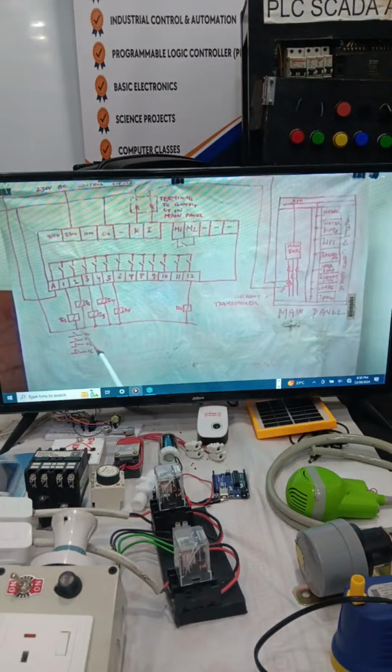To avoid this, we are using one small relay. It will have only small auxiliary contacts, and this contact will not be damaged, and this yellow contact will energize the main power contactors. This is called capacitor duty contactors, because there are many types of contactors, like lighting contactor, motor or switching contactor, but this is a special type, so this is called CDC or capacitor duty contactors.